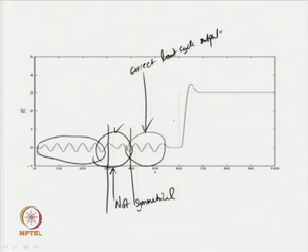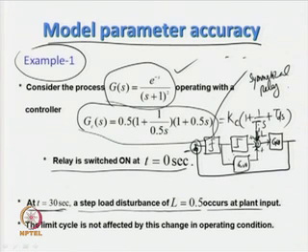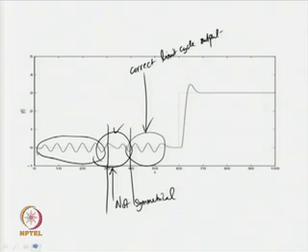Why is that happening? As you know, the controller is in the loop and the controller has integral action. Due to the integral action of the controller, the effects of static load disturbances get nullified or rejected after a certain time. That means, in steady state condition, the effects of static load disturbances are rejected, eliminated. When the effects are eliminated, we get back the correct limit cycle output as it was prior to the occurrence of the static load disturbance. Look at the waveform before 30 seconds; you get a similar waveform in the steady state condition after the occurrence of the static load disturbance.